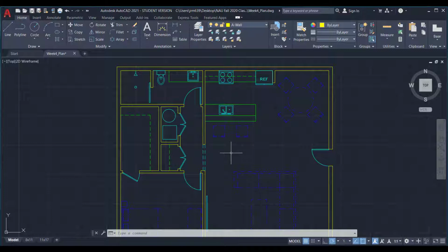So we do something that's called hatching. Hatching means that we fill in with a pattern of some kind, be it solid or diagonal lines or something else. The one and only time that you leave a wall blank is if the wall is a half-height wall. So I think the cutoff is 5 foot, but I could be wrong on that. But if it's a wall that doesn't go higher than 5 feet, then you don't fill it in with a hatch, okay?